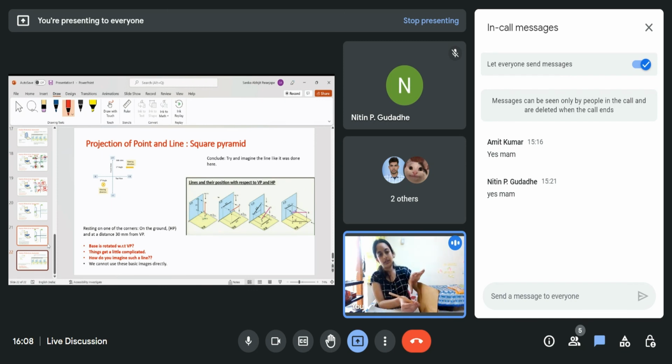So you basically rotate the projected length, and remember that the height from the vertical plane always stays constant. This height is visible in the top view. So you rotate this, you get the apparent length here, and from the top view that you had got, this height, you extend those lines, you get this height, and you get the rotated projected length, and you finally get how it looks in the vertical plane. Okay, so that is it for today.